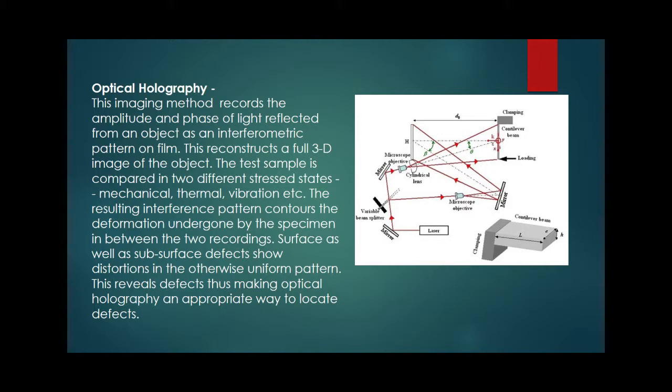So the surface, as well as subsurface, defects show distortions in the otherwise uniform pattern. This reveals defects, thus making optical holography an appropriate way to locate defects.